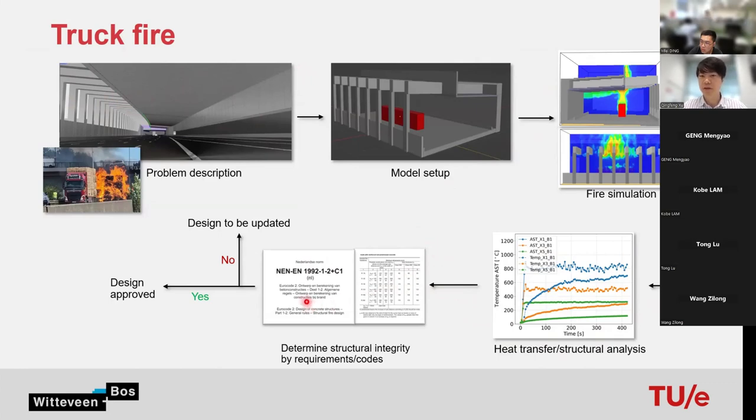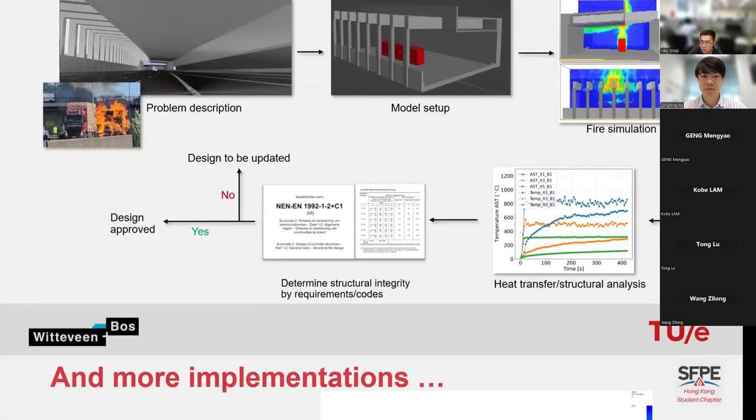From our calculation, for sure this one beam will fail. And then we ask the clients, can you accept the consequences when the one beam fails during fire? If they say yes, then this design will be approved. But if it's no, probably we'll consider making some fire protection for the beam. So this is how it works in fire consultancy here in the Netherlands.